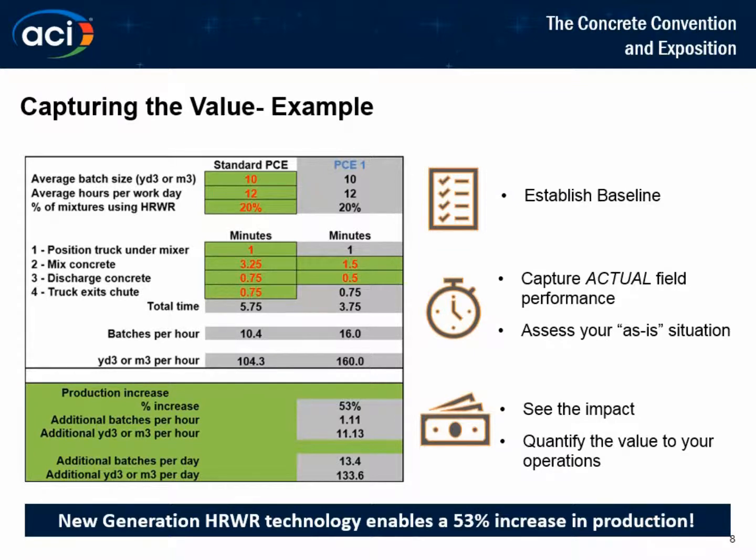How long does it take your batch plant? Or if you're a central mix versus dry batch, how long does that process take? Plus how long it takes to discharge. And in this example, it took about 3 minutes for their standard design to come together to their ultimate workability, and it took another 3/4 of a minute to come out of the central batch into the truck.